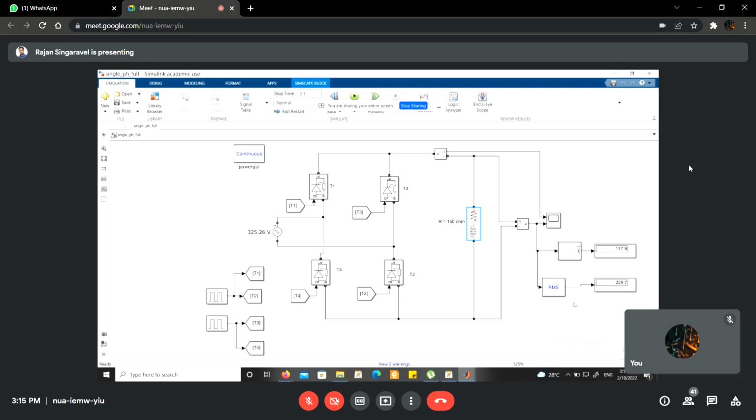Here T1 and T2 are still conducting because the current is still greater than the holding current. But by voltage polarity, T3 and T4 are forward biased, and we have also given the triggering pulses. In that scenario, immediately after supplying the firing pulses, T3 and T4 will come into the picture. T1 and T2 will be thrown into off mode, or the cutoff mode.